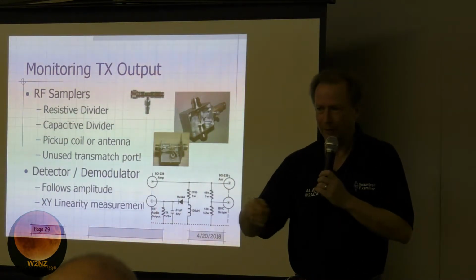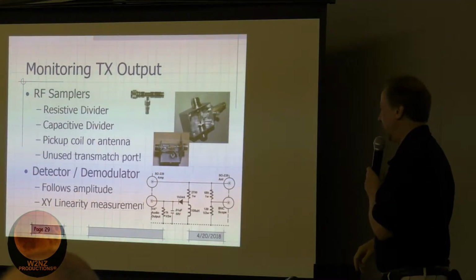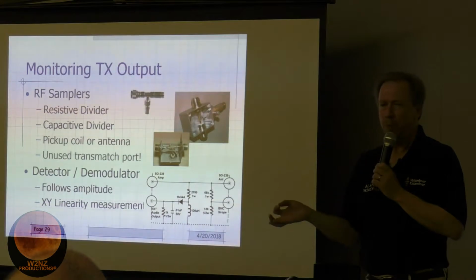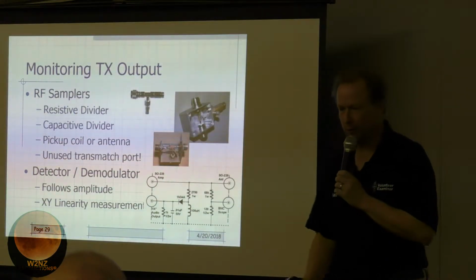Right, you just hook the coax up to it and hook it up to the scope. Yeah. I would poke a hole in the back, put a BNC on it, and a little probe in the cavity. There you go. That's the equivalent of that. So it's a lot safer. It's not connected to anything. You can't accidentally connect to it, and do it that way. But that's another quick, no parts way of actually doing an RF signal monitor.